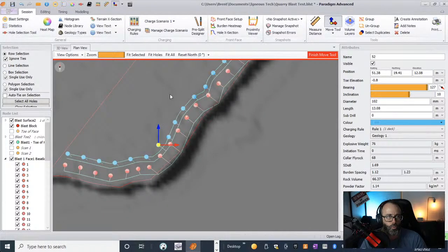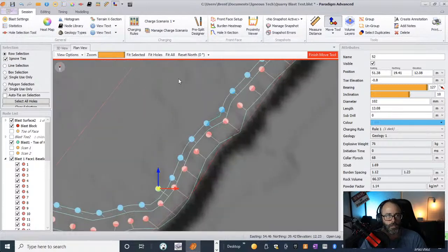Now, what I'm trying to communicate in this position is that if you increase the angle on this second row here, you are making these blast holes more in a line. However, this has a consequence: the next row has to be closer if it's 5 degrees. So whatever you do in this scenario means that sooner or later in the bulk of the shot you're going to have to accommodate some overburdening of the toe and some underburdening of the toes, and you just have to decide on where that energy is stored.